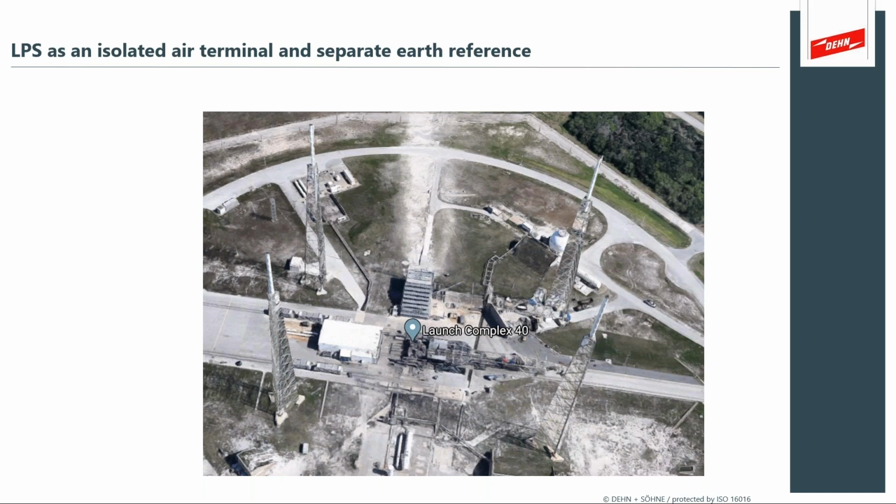And the people that are launching rockets with hydrazine and liquid oxygen are very worried about all sources of lightning damage. So they're reducing everything. I can assure you at this site, they've got SPDs, they've got filters, they certainly have these tall structures around it, which provide isolated air terminal, down conductor, and earthing systems that don't pollute the ground of the actual space vehicle. So in this case, isolated air termination systems are providing every benefit possible.